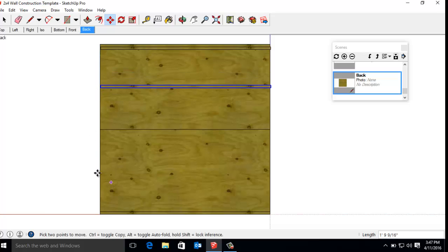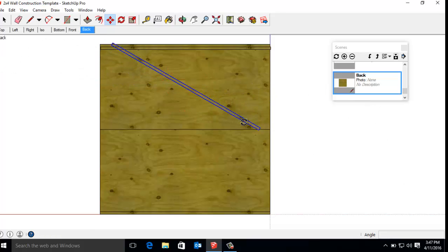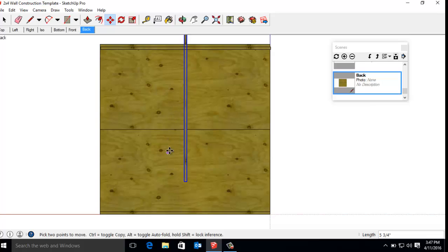Now we're going to rotate this thing so that it runs vertical. If you put your mouse over the move tool, it gives these things. See these little hot points? That allows you, the rotate thing comes up. You don't have to choose the rotate button. You can just click and drag, just like the same thing in the bottom right, it'll tell you when it hits 90. It even snaps there. And then I'm going to take this, and I'm going to be smart and grab an end point.